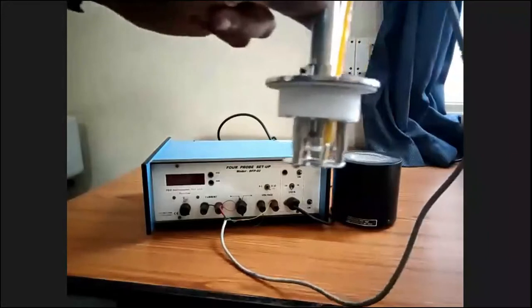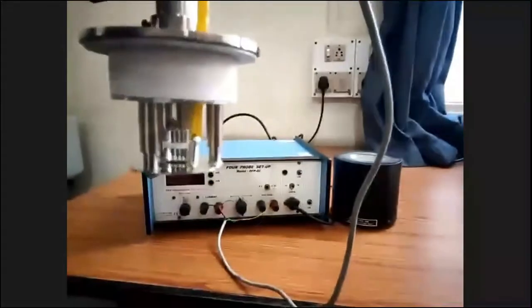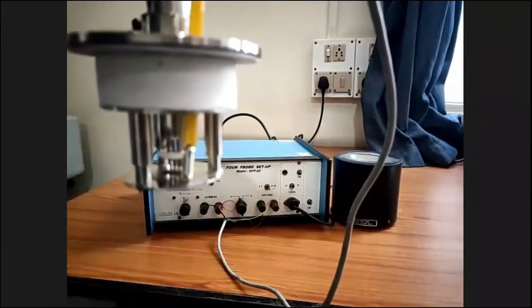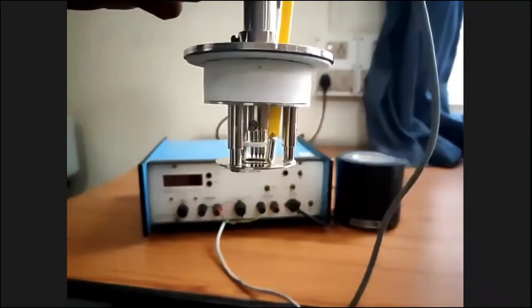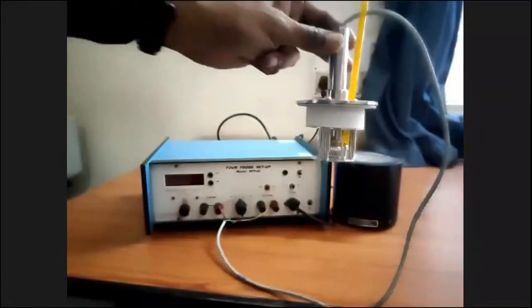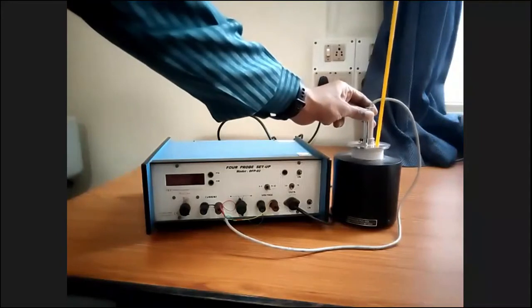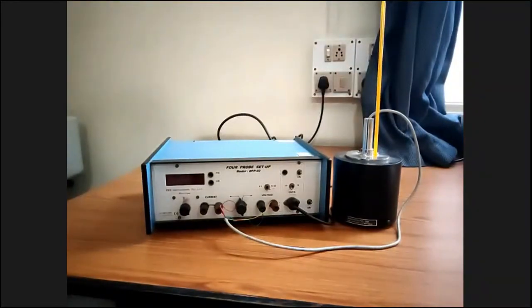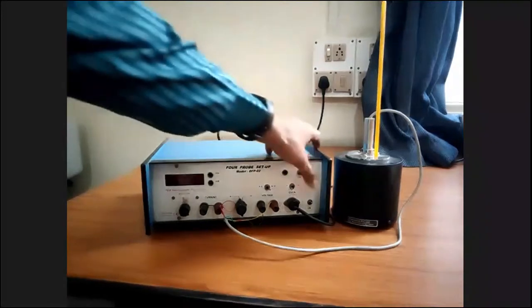Now you can see there are 4 probes, and exactly below the 4 probes we can find the semiconductor placed in rectangular shape, and the mercury bulb of the thermometer is very close to the semiconductor. By this you can measure the temperature of the semiconductor, and the total setup is inserted within an oven. And this oven is connected with the 4-probe setup. The power is actually supplied from the 4-probe setup to the oven. Now I switch on this oven.